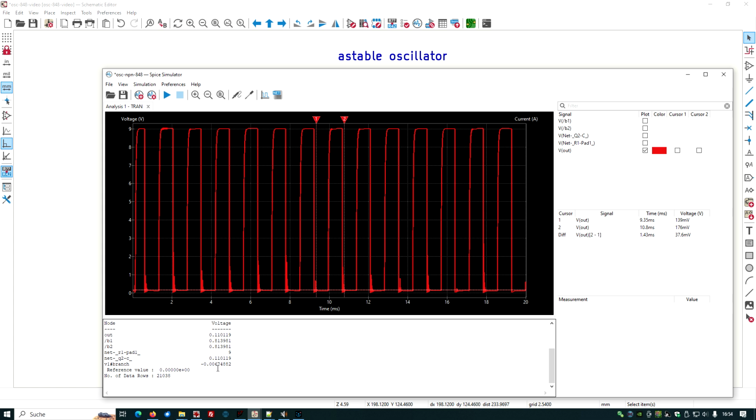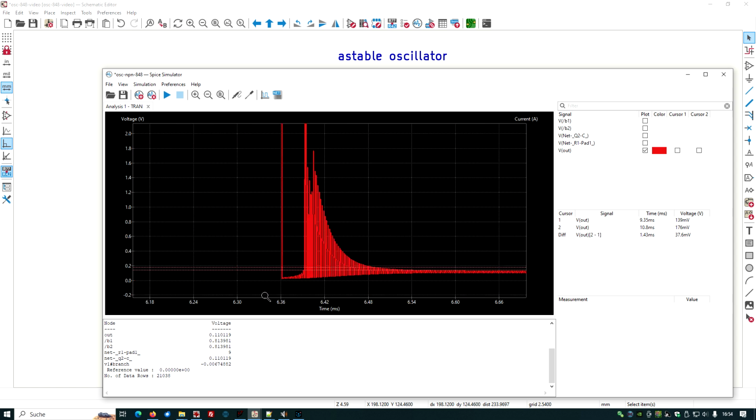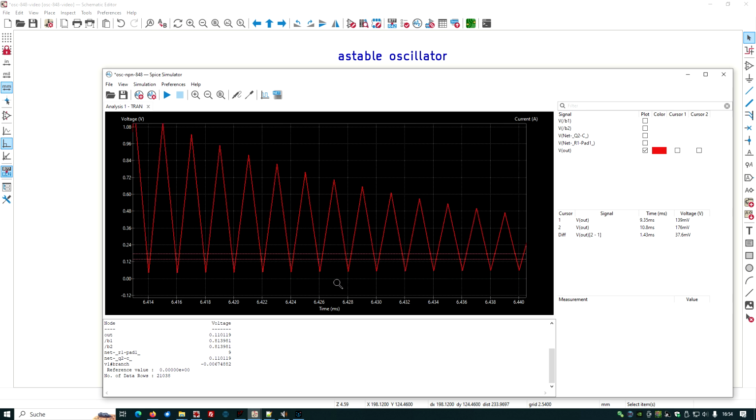But something is a little strange when I look in detail into our output graphs here. Let's have a look. Let's enlarge it. There seems to be some oscillation. And in fact, it is from time step to time step. Every 1 microsecond, another microsecond, we have this ringing. And in fact, it's an artificial oscillation, so-called trap ringing. And we want to get rid of that.